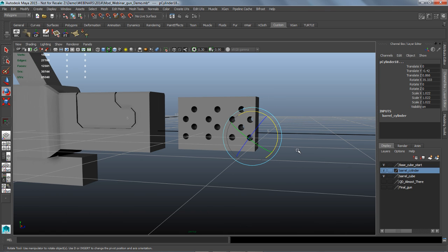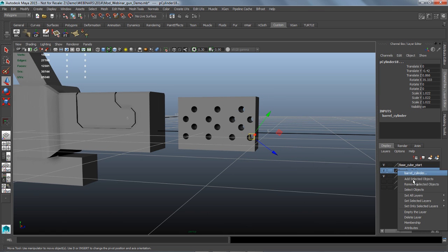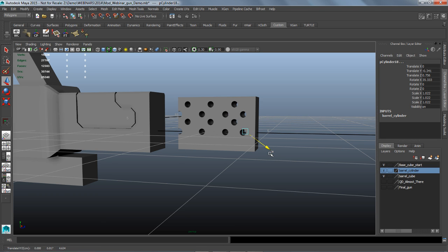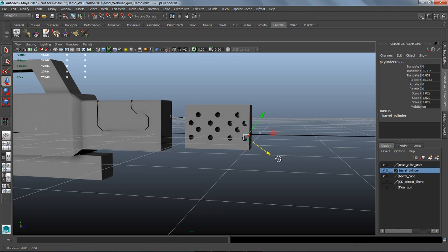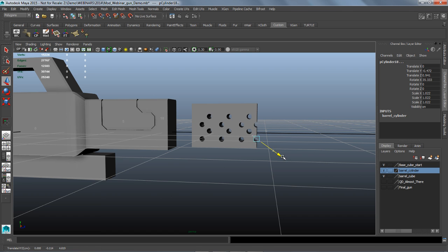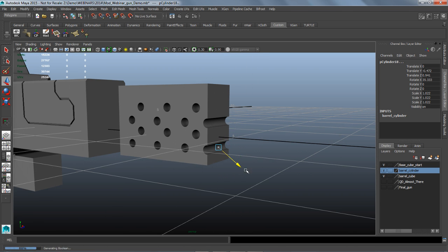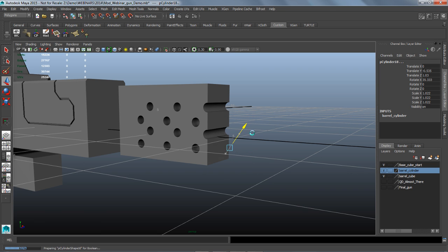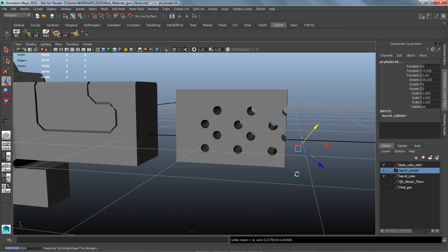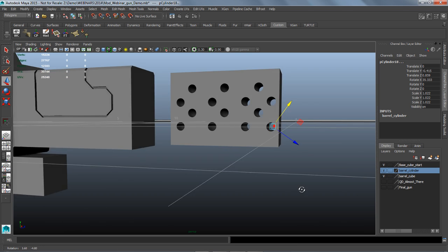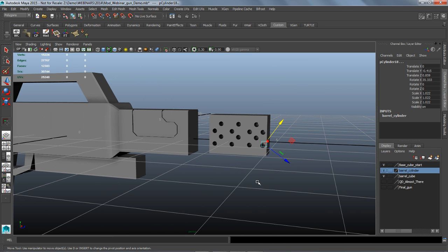I'm actually rotating only the one there right now. Select all those objects there, and then I can change them or augment them. And if I bring them to the edge, you see we got a really clean Boolean in there. So you can see that we finally have something that's going to work really nice and clean as you're modeling within Maya. So let's move forward with that.